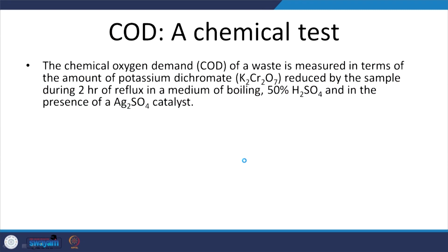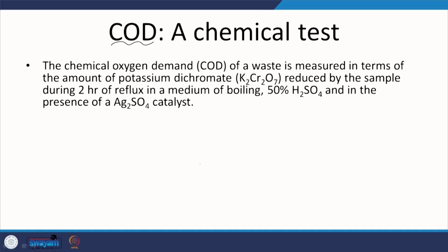Let us move on. As I mentioned, COD is relatively faster and relatively more reproducible, unlike the BOD test, which is slow, and depending on the kind of waste and whoever is doing it, you are going to have issues with respect to reproducibility. COD, though not really such an issue, is relatively costly, because the ingredients are costly, but one aspect is that the amount of lab space required is pretty much less.